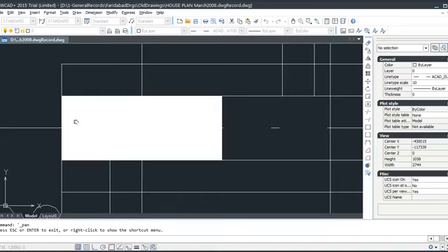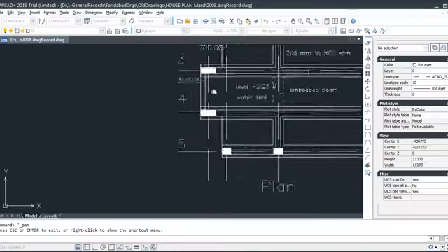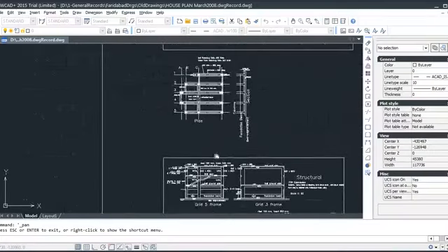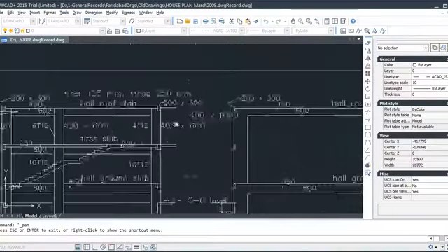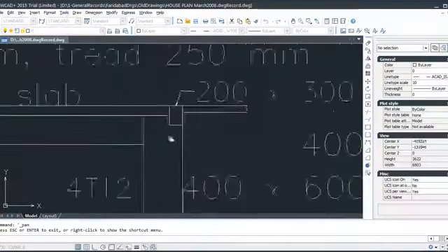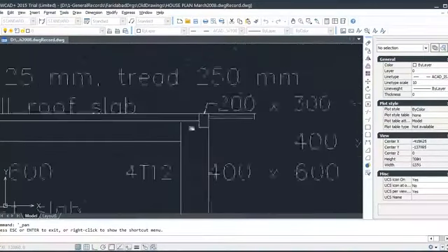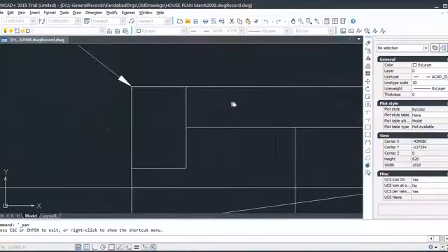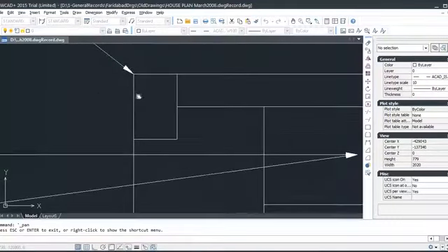But let us say 1/3 of this is damaged during fire. So in actual sense, we get a reduced section for every column and for every beam. Beam also, as I said, let us say this is a beam. Fire applies here, this is a cantilever here. Fire happens, and fire applies here, and here, up to here at least, maybe more. But this fire will damage these three sides.